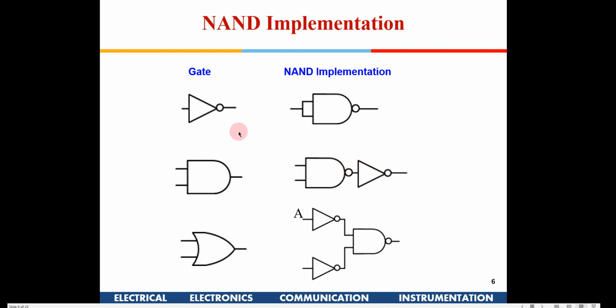Because when we simplify a Boolean expression in K-maps, if you are going to simplify the min terms, we are going to get a function in sum of product form, right? So you will have AND and OR only there, and you will also have some complements of certain functions. So these three transformations are all that is required for transforming any simplified min terms from K-maps into logic circuit implementations with NAND.